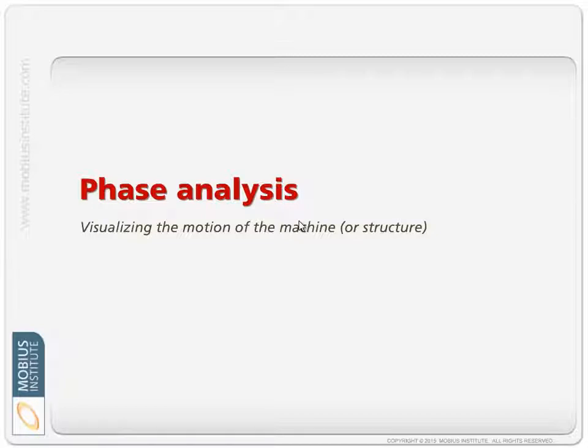All that force translates into movement of the bearing. It moves up and down and side to side with, for example, unbalance. But it moves differently if it's misaligned, and it moves differently if there's cocked bearing and other sorts of faults. So that's what phase analysis does. Phase analysis lets us step back and think about what's actually happening to the machine as a whole. How is the vibration, or how's the fault condition causing the machine to move? And that tells us a lot about the fault.